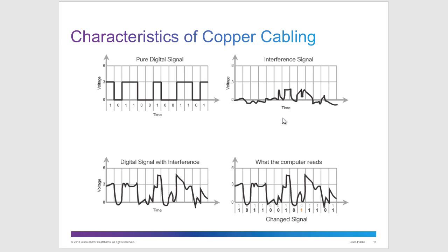and that means it's going to be more susceptible to interference. Where these peaks are this high up here, the further your signal travels, it's going to deteriorate. So maybe your peak's way down here, and this little bit of interference is going to turn a 1 into a 0 because the signal has run through too long of a cable, or it's just had that much time to deteriorate. So that's something that can happen with signal attenuation, which means that it has deteriorated over time.